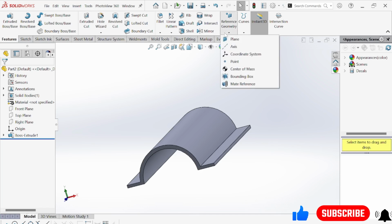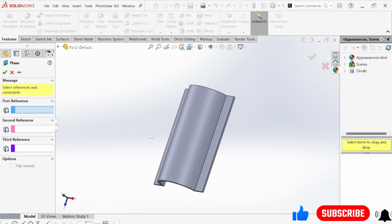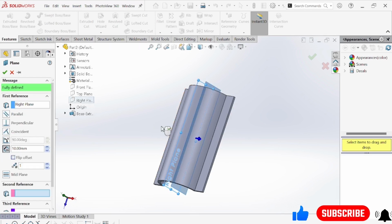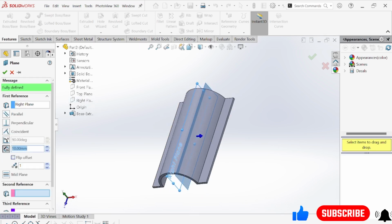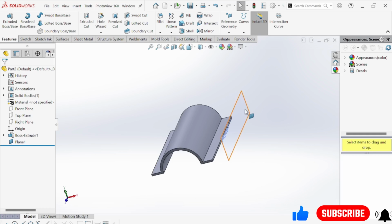Go to reference geometry, select plane, because we are going to work with the plane. The overall length of this part is 100 mm, right? So let's select a plane. This time select the right plane. Right plane is fine. And this time give dimension 50, and make this one okay. Now here it looks absolutely fine.